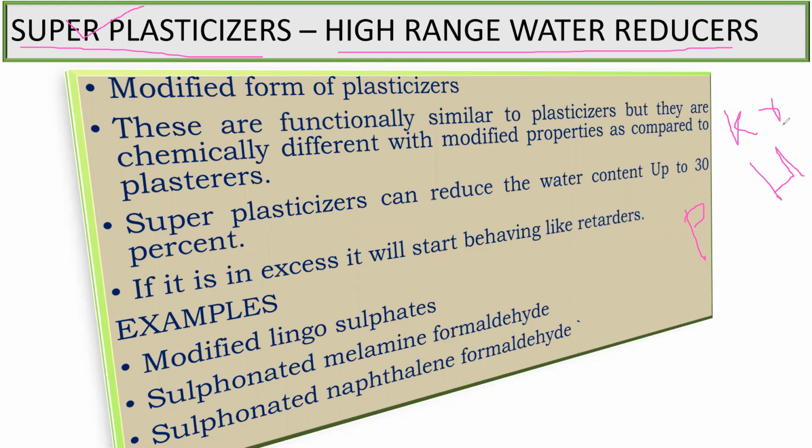The principle is the same: to reduce the water content to increase the workability. But for a very low water cement ratio, if you want more and more workability, then we make use of the super plasticizer. That's the basic principle behind them.